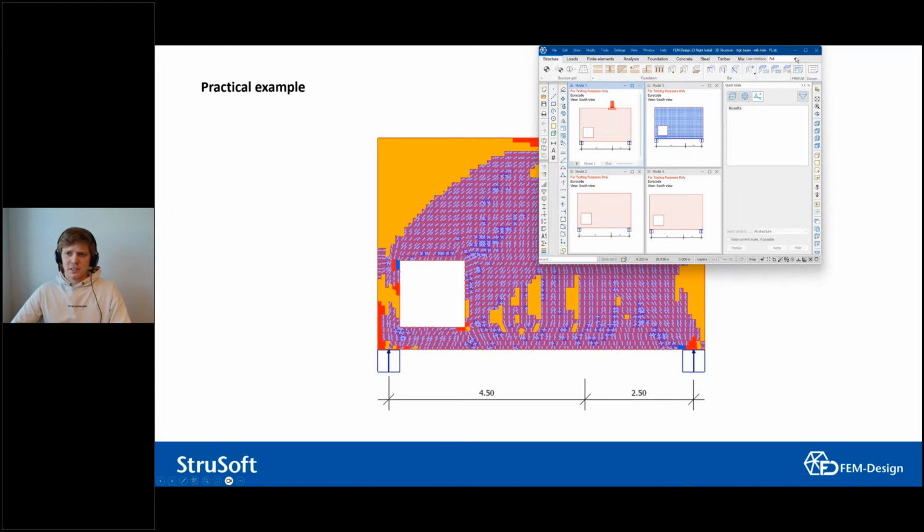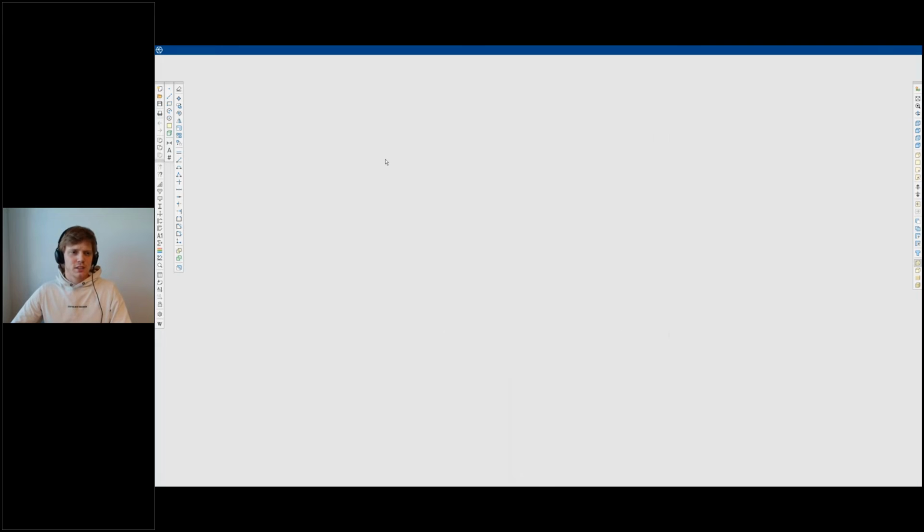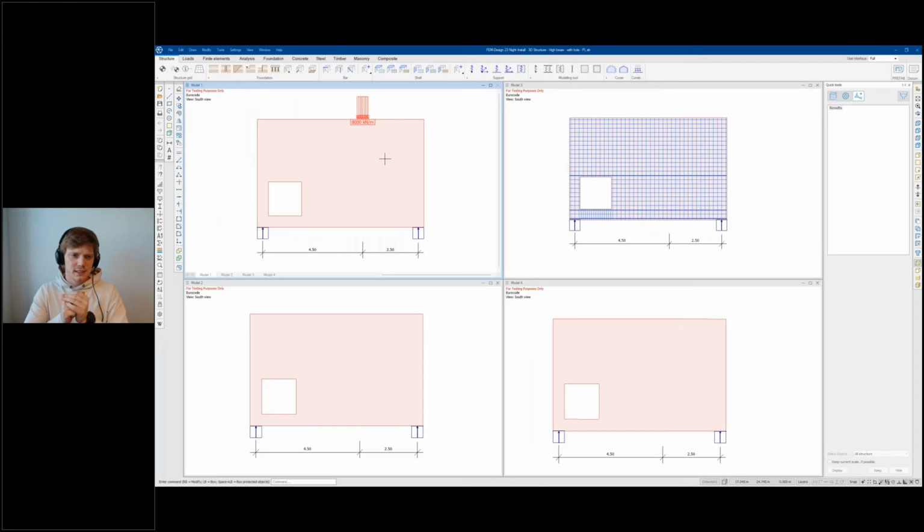I have tested a specific scenario. I have modeled this reinforced concrete wall. Over here you have my boundary settings. I have the vertical support, I have a loading, and here's my reinforcement. The important thing to note is that I have a standard reinforcement net here, and I have some concentrated bars on top of the hole, and I have some at the bottom, and then I have some included reinforcement here for the shear.